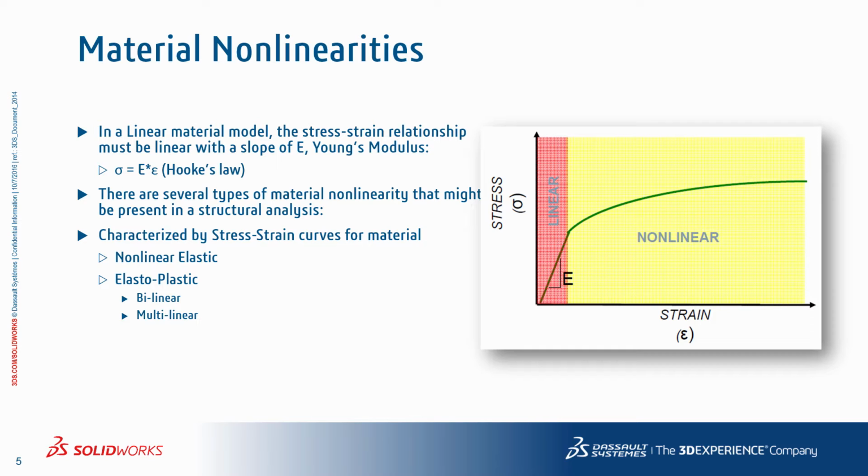The other material models supported in SOLIDWORKS Simulation include hyperelastic materials for elastomers and viscoelastic for time-dependent response such as creep. Finally, a nitinol model is available to simulate materials such as shape memory alloys like nitinol, typically used in medical stent applications. Keep in mind that these material models do require a detailed knowledge of the material behavior, as they don't behave like any other common structural materials.